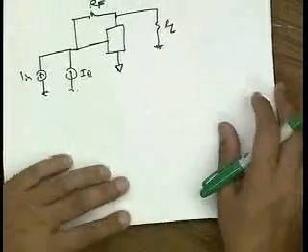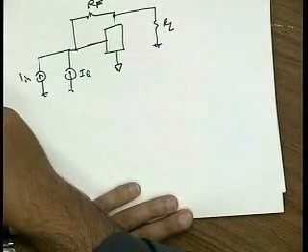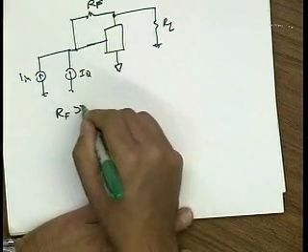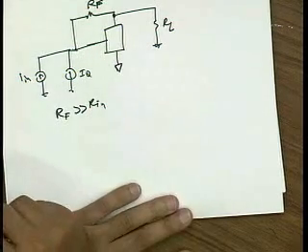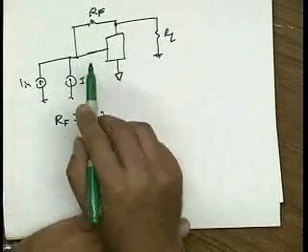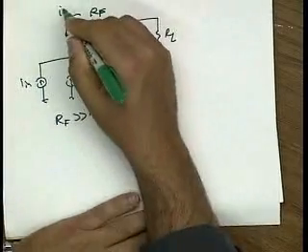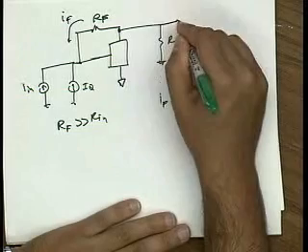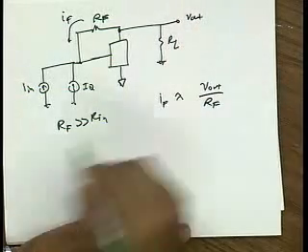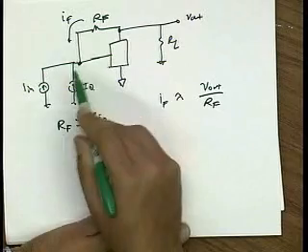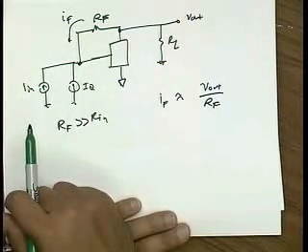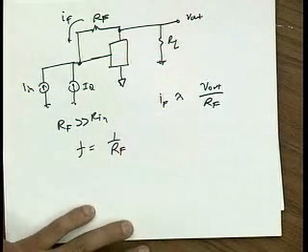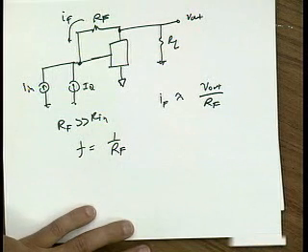So you're given in the problem that RF is much bigger than Rin. In other words, the input impedance is very low. That means that the feedback current, IF, is approximately Vout divided by RF. Okay? Because Vin practically doesn't move at all. It's very low impedance. So that means that F is simply 1 over RF. Okay? Any questions about that?